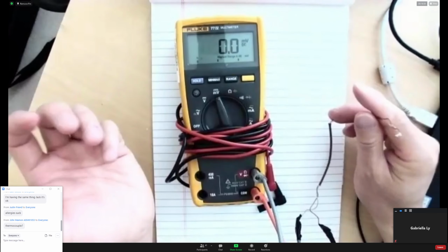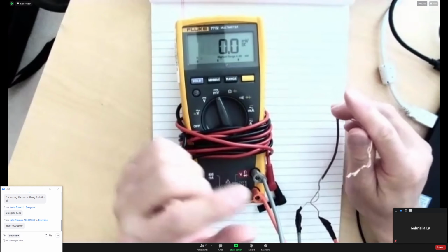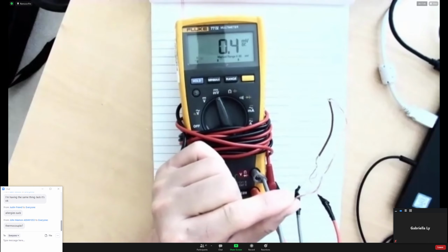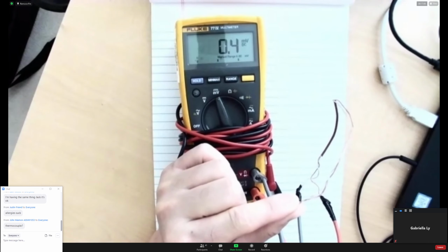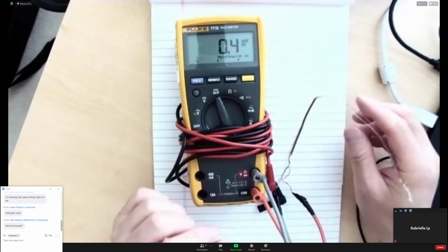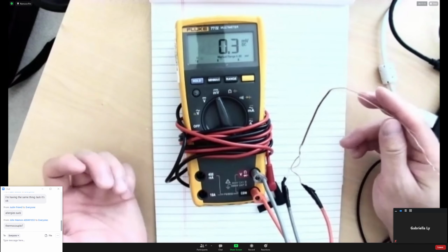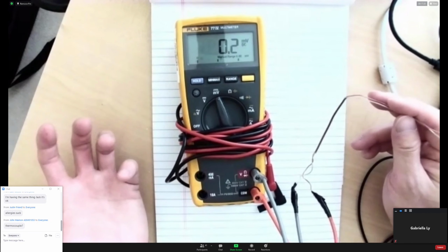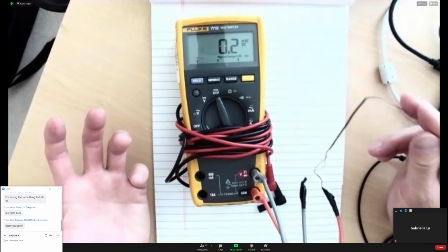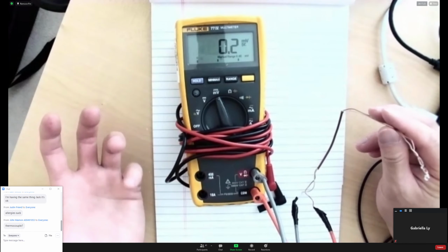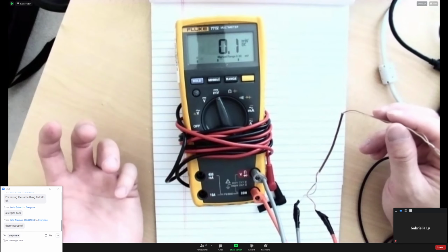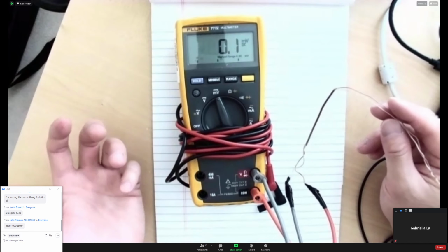But when you change the temperature on this end, they only give you a very, very small voltage down there. So this voltage is basically too small to do anything. If you really want to use it to measure temperature, you put in a certain type of amplifier to make sure the voltage is big enough.